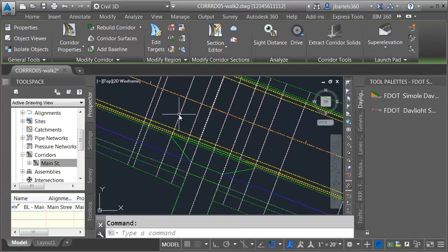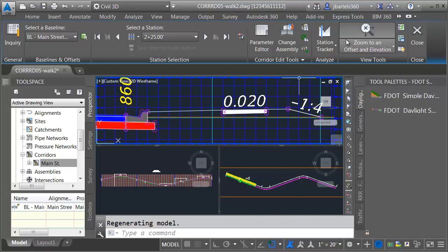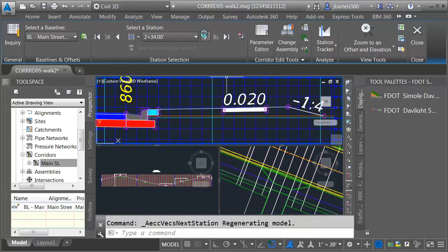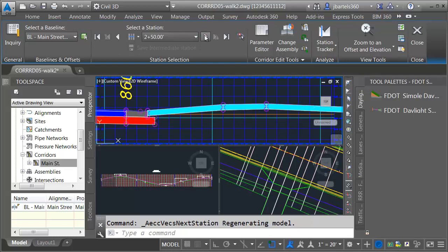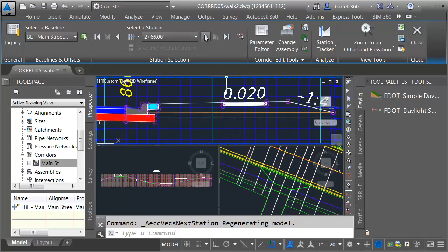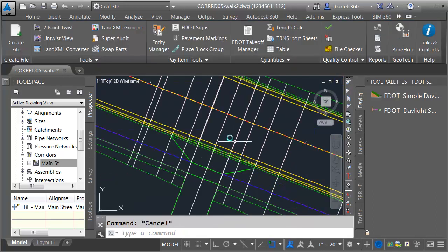One last time we will select this and go to Section Editor. Let's zoom in and we will lock that location. Zoom in here and we'll tip this over so there's where the driveway starts. Flanging out, there's right up against the driveway. We still have sidewalk. Here we have the driveway, middle of the driveway, edge of the driveway. Here's where the flange starts, right at the edge, and then the flange is heading back down, and then we have the driveway removal. Let me close this.